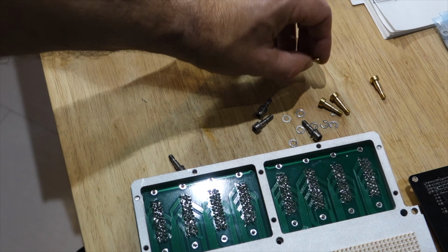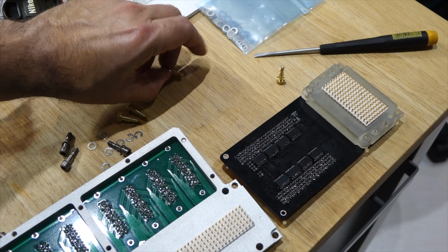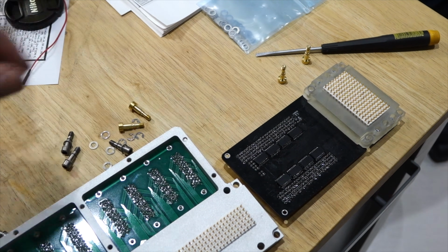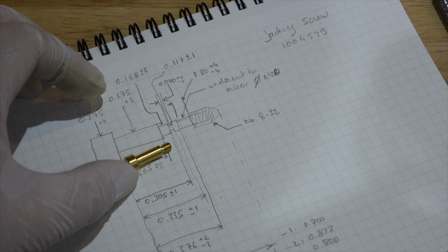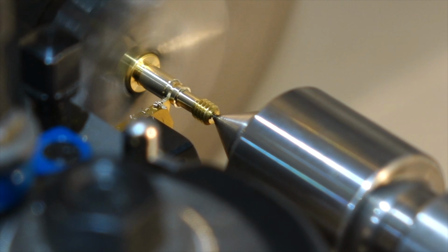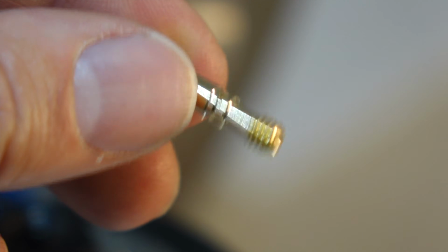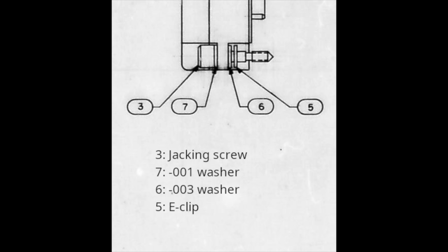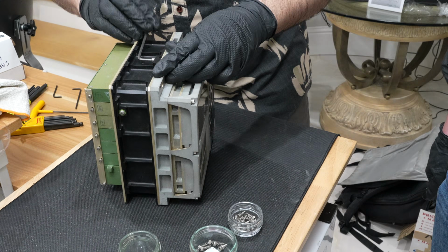These special screws are used to pull halves of assemblies apart when there is a connector joining the two, so there is no risk of tilting the pins. I had to machine a few of these NASA screws when we rebuilt our main connector assembly for the AGC. That's a screw that's easy to damage if you don't realize it's a jacking screw and try to force it out before the other regular screws are removed, which is what had just happened here in the past apparently.